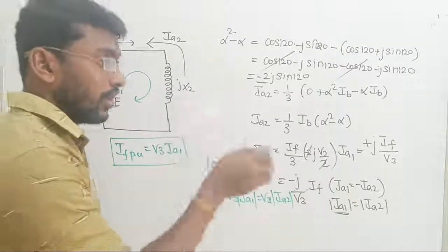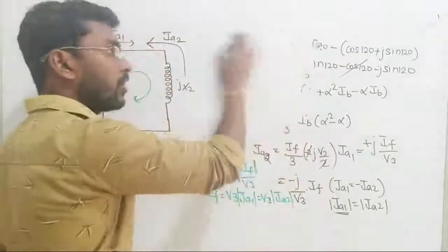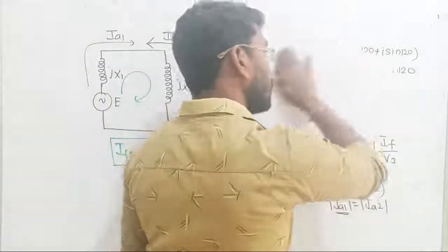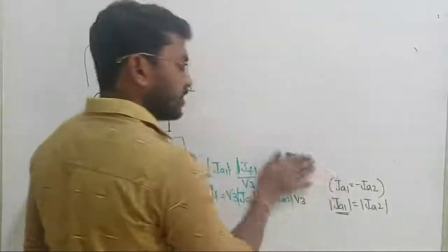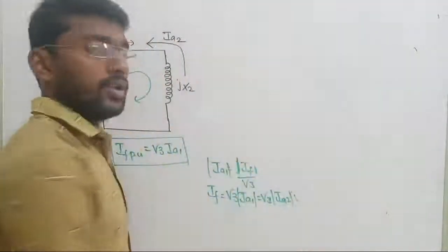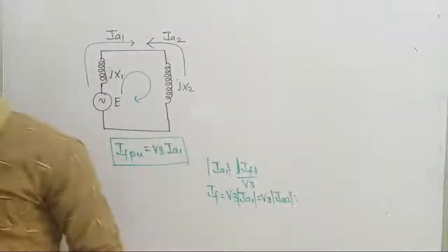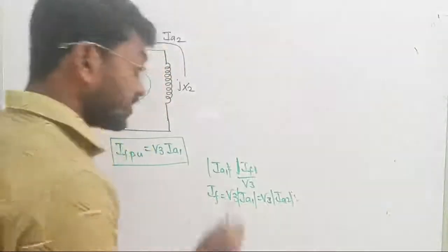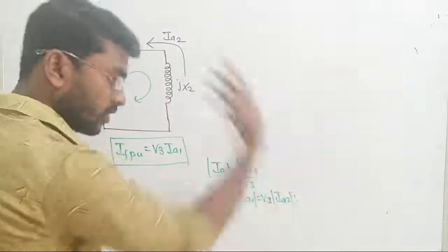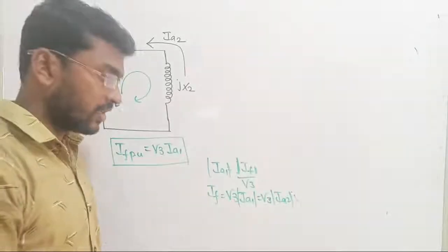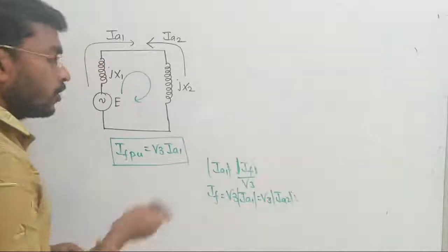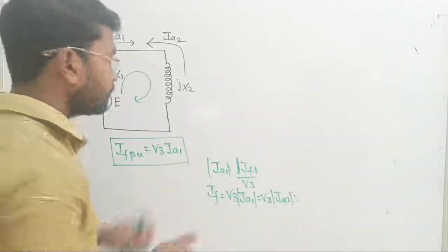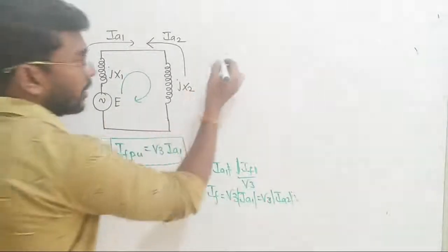Guys, don't follow any notes. I know if you are following your notes, they derive the expressions for voltage and current, and then link the relation. Of course, that is the actual procedure. But in your examination, you cannot sit and do all those things, right? That is a waste of time. So think in the simplest way: one matrix is sufficient to bring all the answers for all types of faults. Just go with this procedure, that is sufficient. Do it repeatedly, do it by yourself. Fine, calculate the fault current.